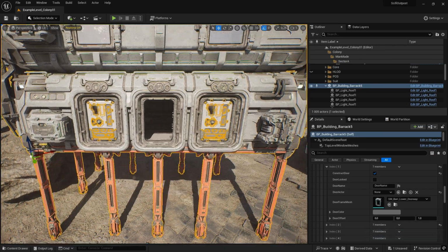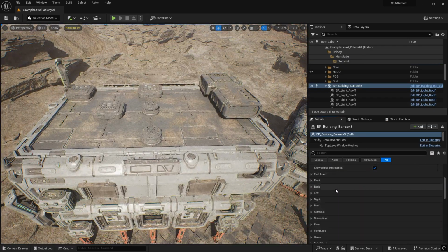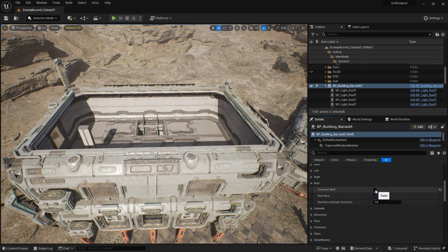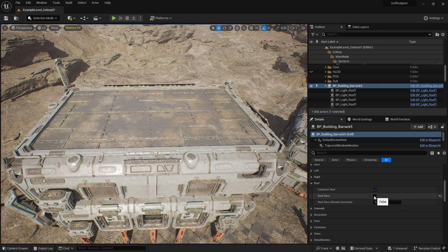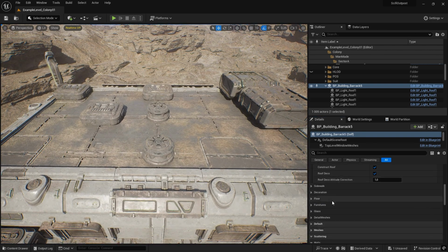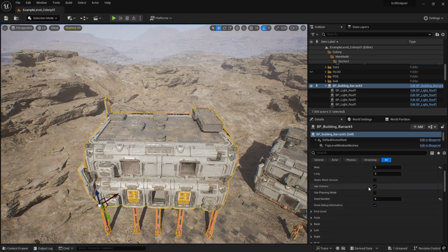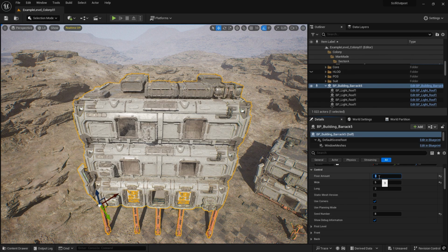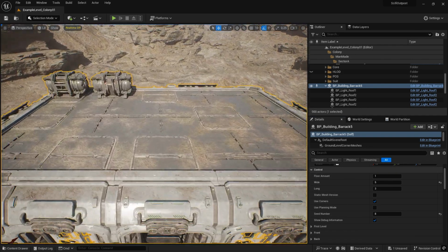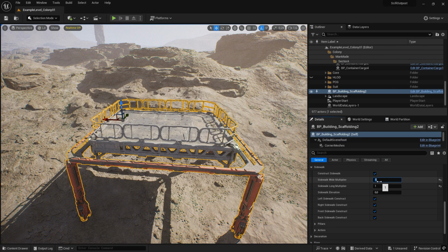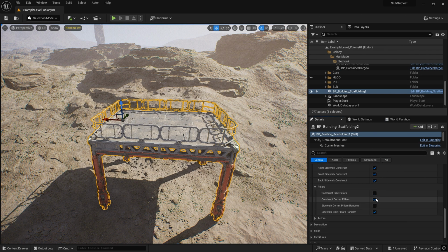Building system will generate a roof on top of the last floor wall meshes. There are lots of controls on what type of roof meshes it will use, offset for those meshes, roof deco meshes, and so on. All of these parameters are stored under Control Roof. You can disable roof construction totally or choose to scatter roof decorations that are specified under Meshes.